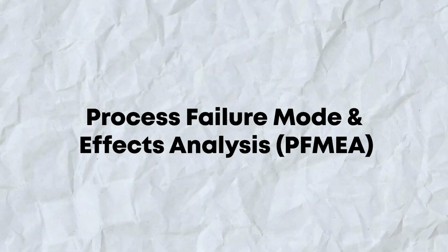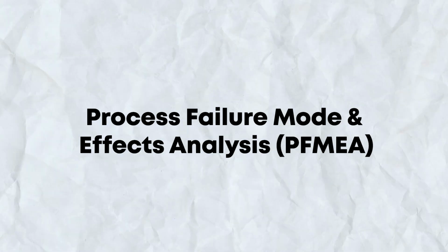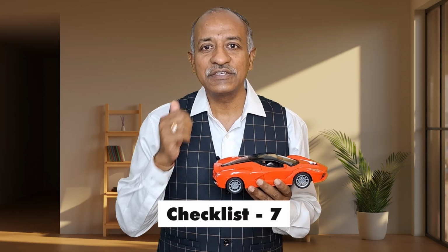Then the next one is talking with respect to process failure mode and effect analysis. If you look into the AIAG first edition, it is talking in detail about that. And there is an appendix checklist number 7, which is talking about the different questions with respect to the process FMEA. When we talk about process FMEA, the intent is that whatever customer requirements are coming, whatever is an output of design FMEA, whether all those things have been incorporated in that or not.